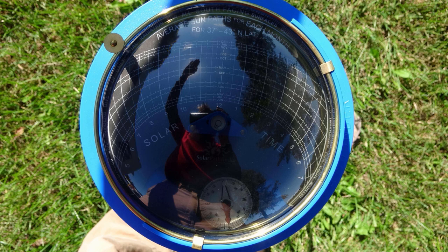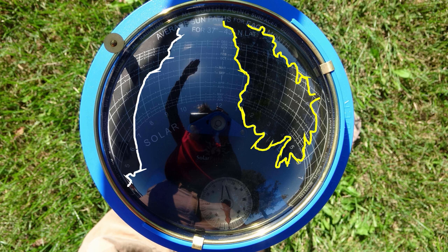And you'll have to ignore the hand gesture that's blocking the sun for this photograph, but this location does have another shadow from the tree that's on the west, and that's blocking most of the afternoon sunlight. If removing an obstacle like either of these is impractical, then you can simply move the Pathfinder to a new location that may provide better exposure.